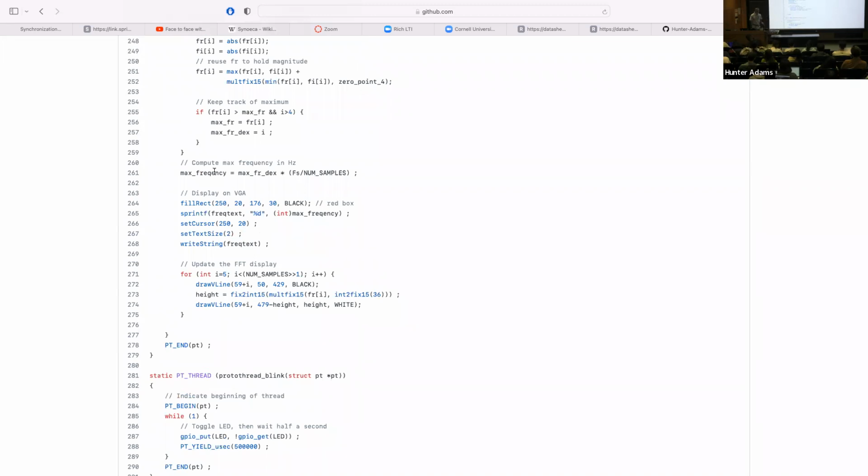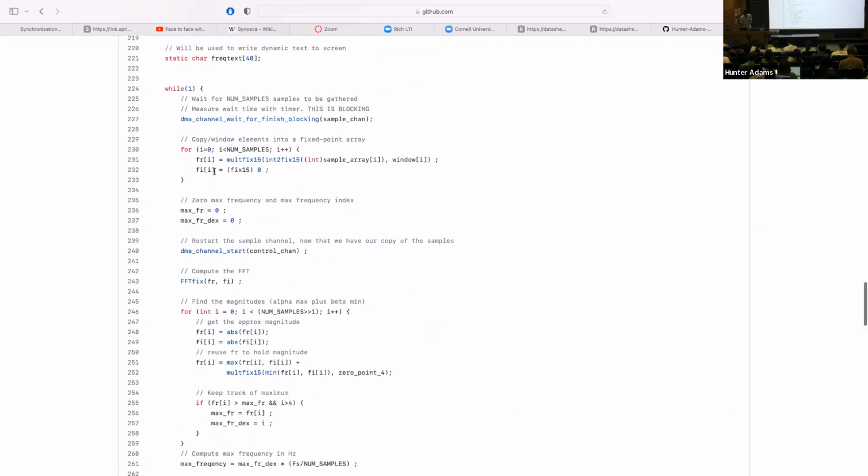If so, it then knows, okay, there is a cricket chirp present in this batch of samples. It then has to ask both core 0 and 1, is it possible that you generated this cricket chirp? And the way that it can learn that information is by accessing the state variables in the interrupt service routines of both core 0 and 1. Those are global variables, so they're accessible to both cores. So what I would recommend is